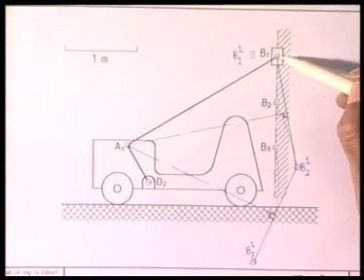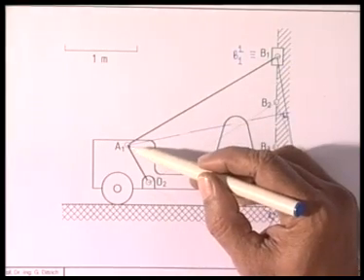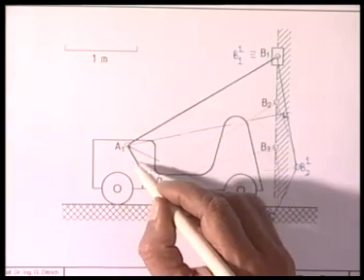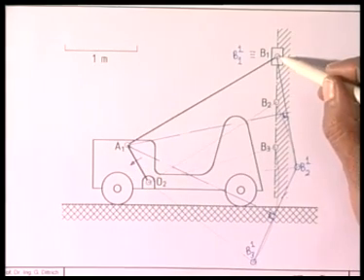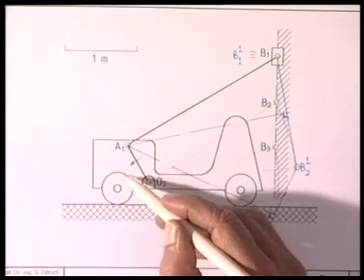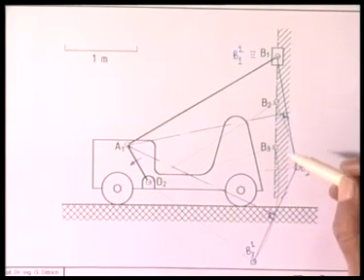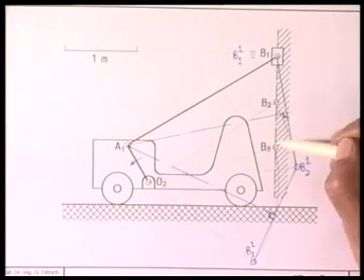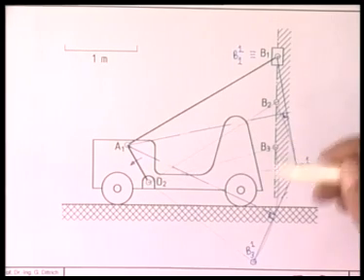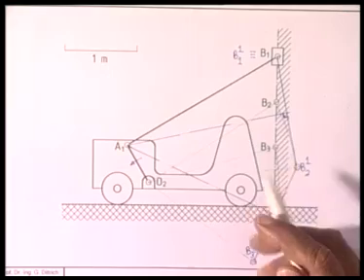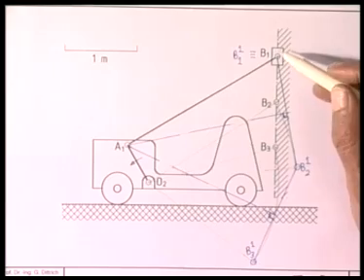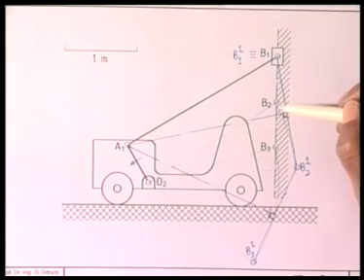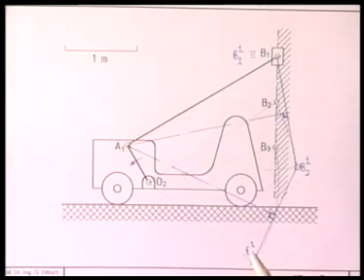A1B1, where A1 is the crank pin, such that the 26 degree counterclockwise rotation of this crank will cause the slider to come from B1 to B2. Further 26 degree counterclockwise rotation of the crank will cause the slider to come from B2 to B3. In the next stage, we will get to a 4-bar linkage such that I can remove the slider, and this coupler point B1 will automatically pass through B1, B2, and B3 when that 4-bar linkage is moved. But that is the second stage of the synthesis.